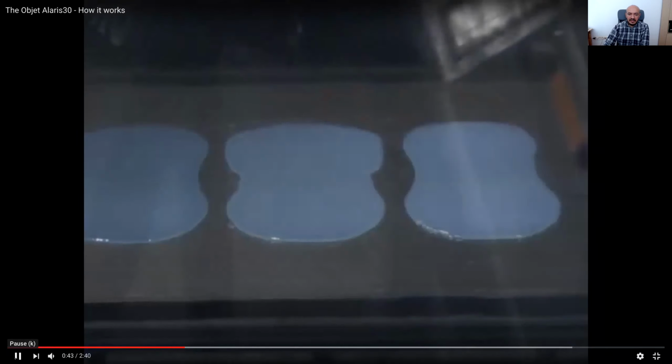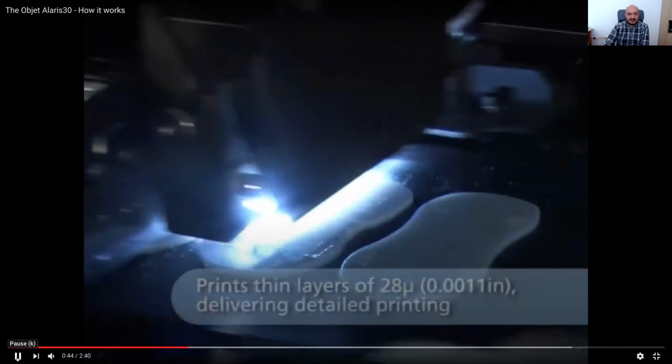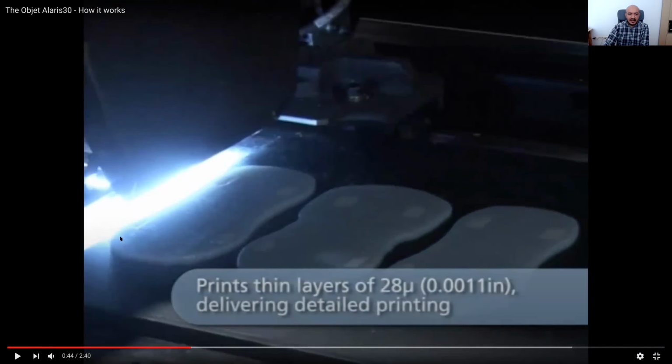Now you see the printing process. They are using a number of jets, and these jets are jetting liquid polymers. While they are jetting, they are also curing this liquid polymer at the same time. You see, they have a light here. So with the help of this light, the polymer is cured and solidified.